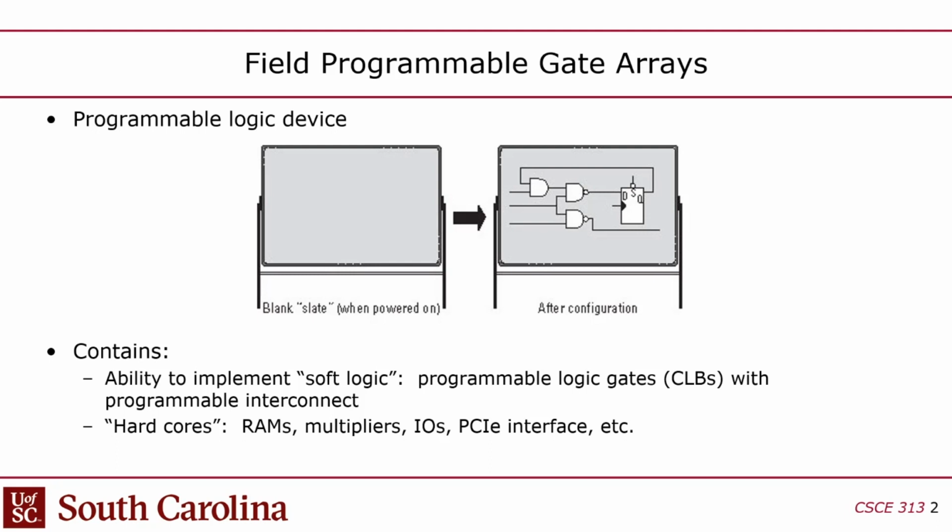and so that was the problem with those. But the other issue too is that even to get a console on those, to say hello world, we had to do it through a pretty flimsy connector and use Minicom, and it was a hassle. With these boards, it's just much easier. You plug in that USB blaster and you get complete control over everything. That's what FPGAs are for.